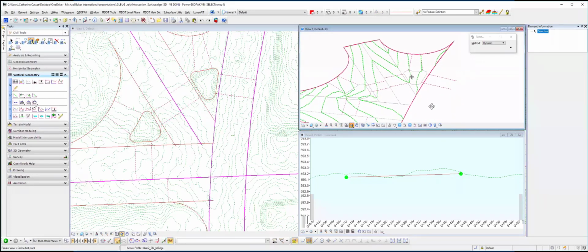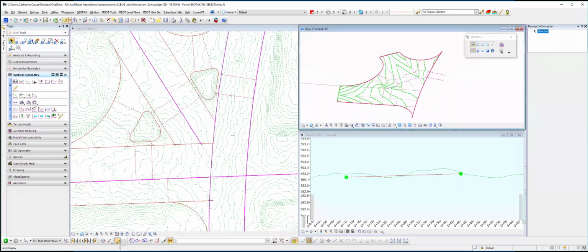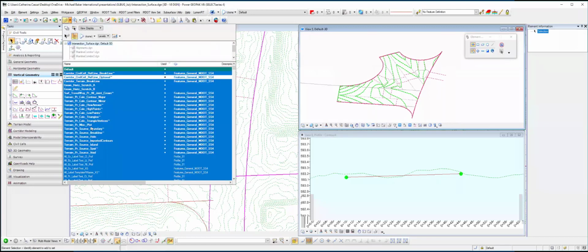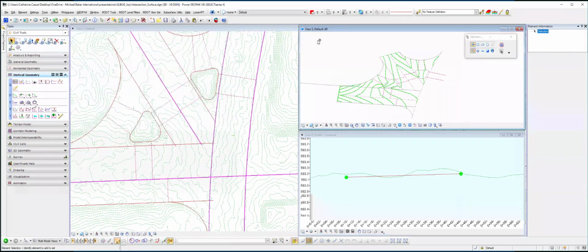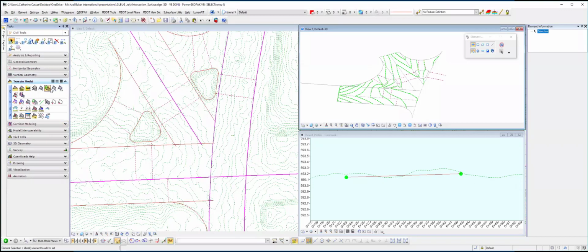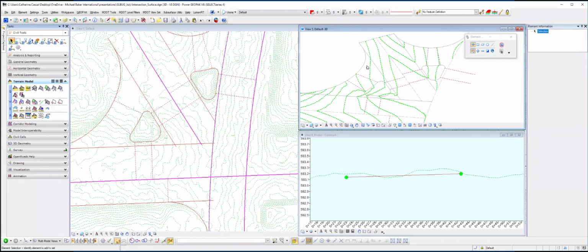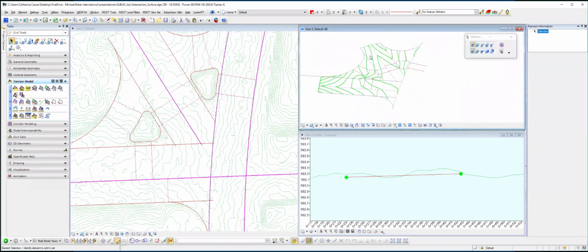So once you have all that, you can create an overall surface. That's a pretty easy scenario. Normally what I would do for that is just to select all of those elements, and typically not these, and you do the terrain model, terrain from elements. And these are all break lines when you do that. So when you hit create terrain from elements, you want to make sure you're bringing them in as break lines. You might think about the boundary from that perspective.